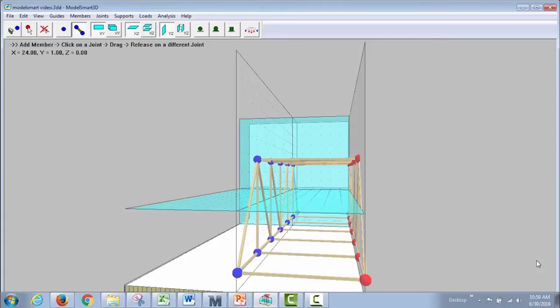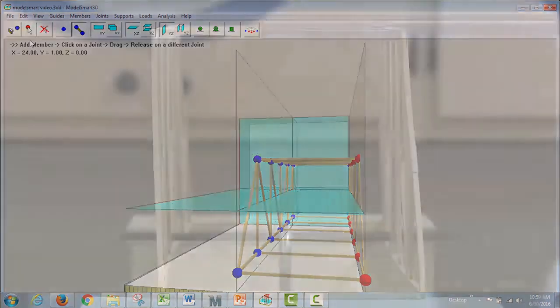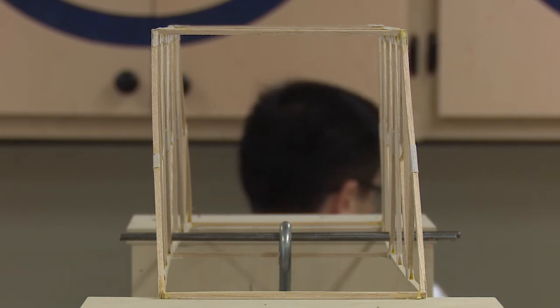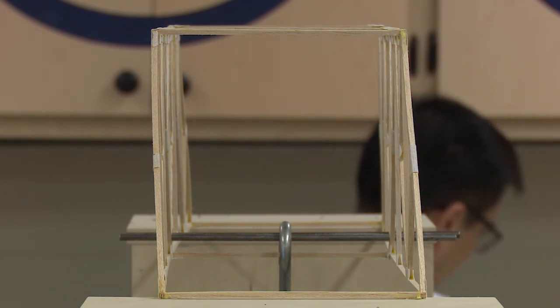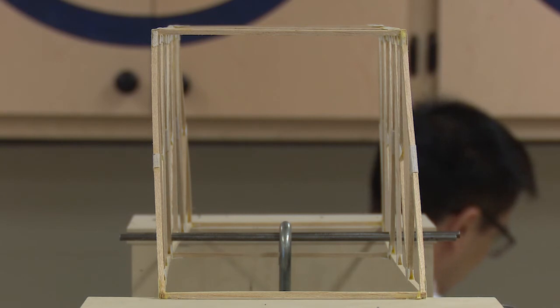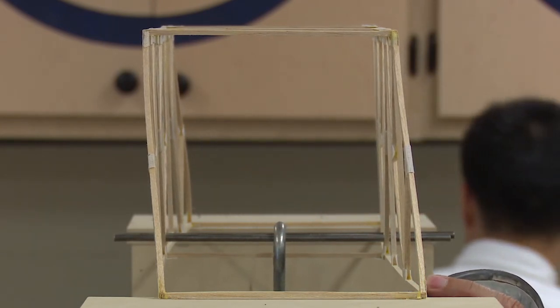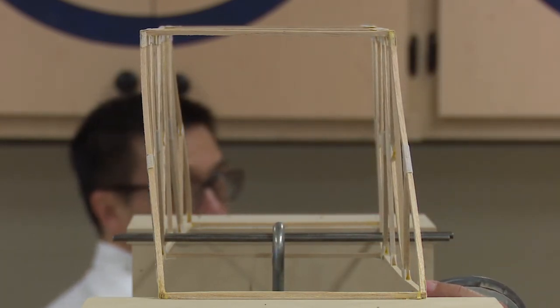You can imagine the two sides are very similar to two pieces of cardboard. In the plane of the cardboard, your bridge is really strong and really stiff. In the direction perpendicular to the two sides, there's really nothing or very little to keep your two sides vertical and upright. If you build your two sides slightly out of plumb, this is even made worse. Once you start adding load to your bridge, if you have any initial out of plumbness, your bridge basically starts leaning over and it still fails by this leaning action.